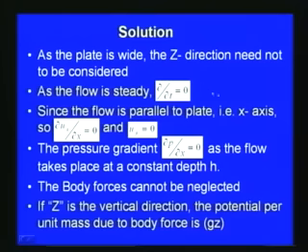So, once the problem statement is known, we try to see what assumptions we can put forward such that we can simplify the governing equations. Here for this typical problem we assume the flow to be steady, the flow is parallel to the plate, and the pressure gradient del p by del x is equal to 0. These are the essential assumptions for this problem, so that we can simplify our equation.